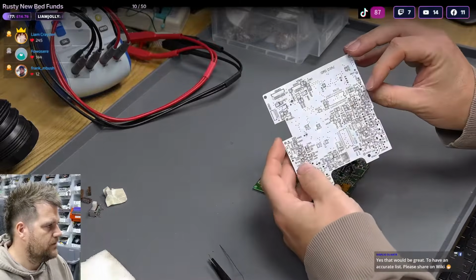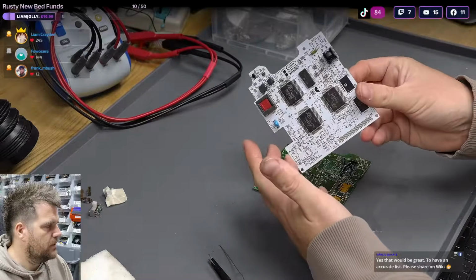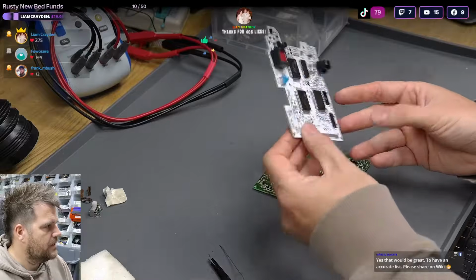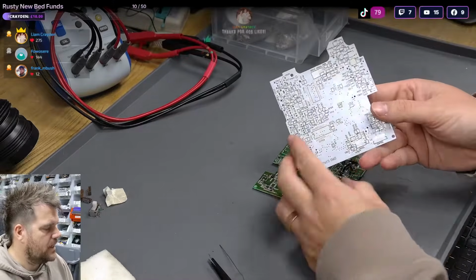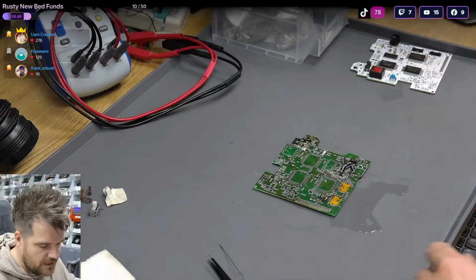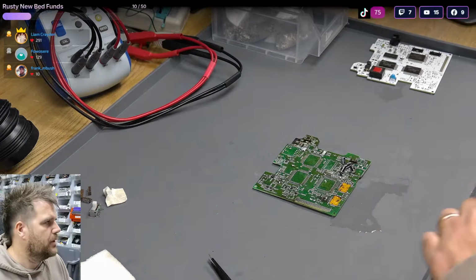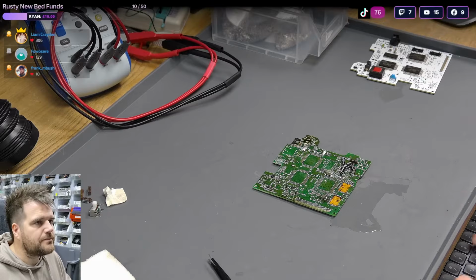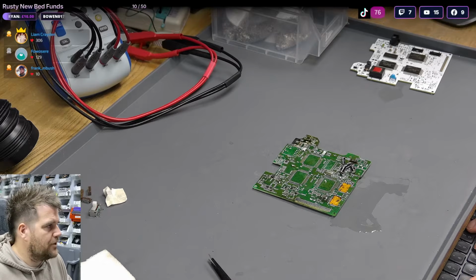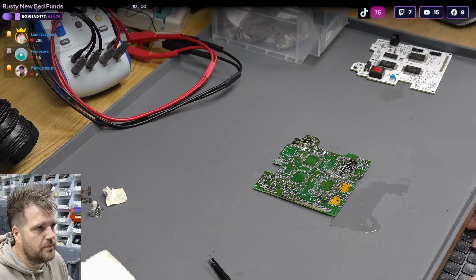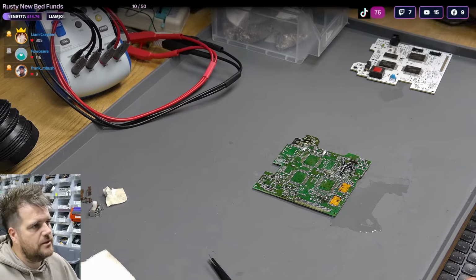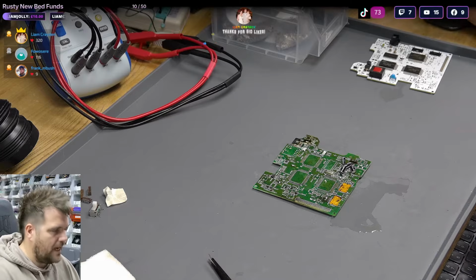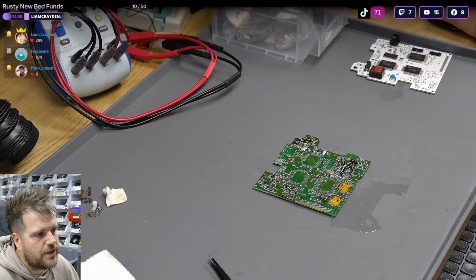We're transferring very slowly every component over onto the board, working our way down this front side and then tackling this disastrous back side after. We're testing every single component as we go, to measure the values and figure out what they are, so that we can have the factory assemble the boards for me in future, and I don't have to swap all the resistors and caps over every single time. I can get most of it pre-assembled at factory.